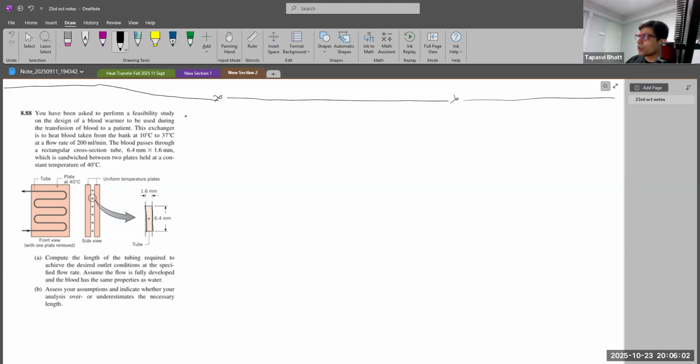And compute the length of the tubing required to achieve the desired outlet conditions at the specified flow rate. Assume the flow is fully developed and the blood has the same properties as water. Okay, so blood has the same properties, so we have to use water's properties. And we know that the T mean at the outlet is 37 degrees Celsius, T mean at the inlet is 10 degrees Celsius. The cross-sectional area As is...